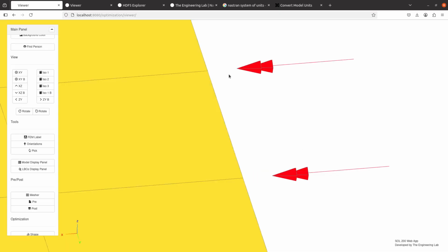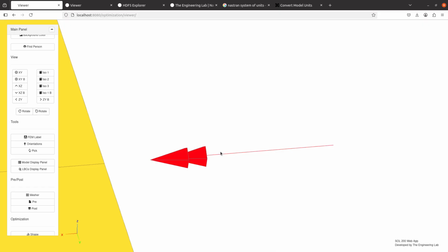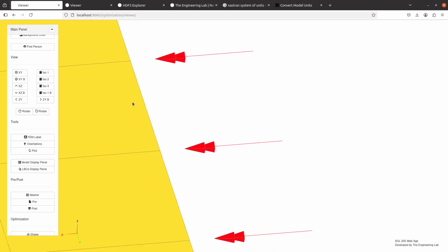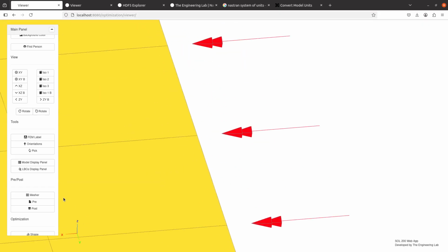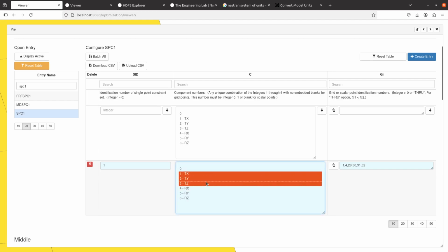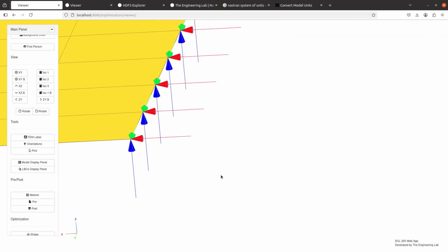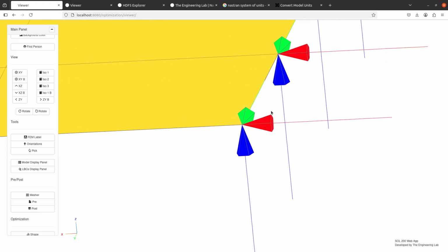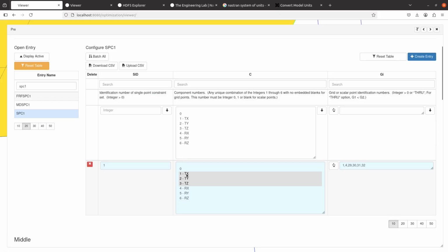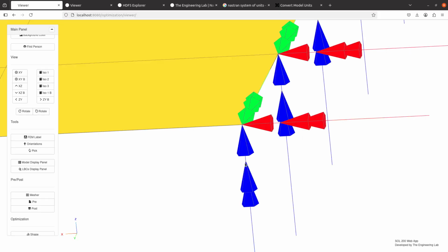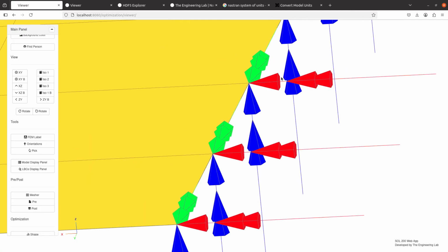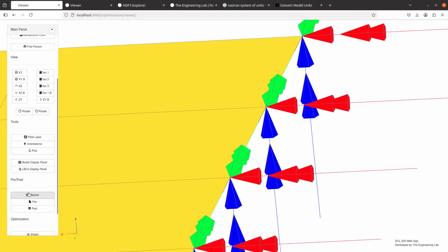That will actually give you a double arrowhead. So the rotation at these degrees of freedom are 0. And what happens when I constrain 3 degrees of freedom? So this tells me that translation in all 3 directions are constrained, and then let's go ahead and make sure all 6 degrees of freedom are constrained. So that's what I did. Delta and thetas are 0 for these degrees of freedom.